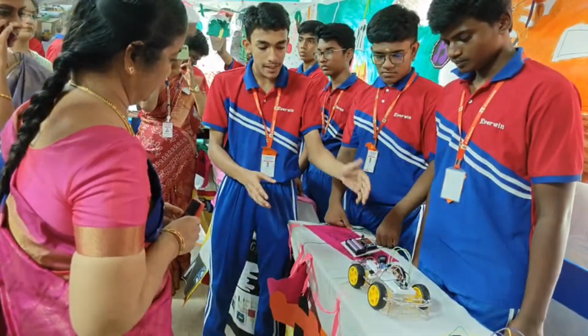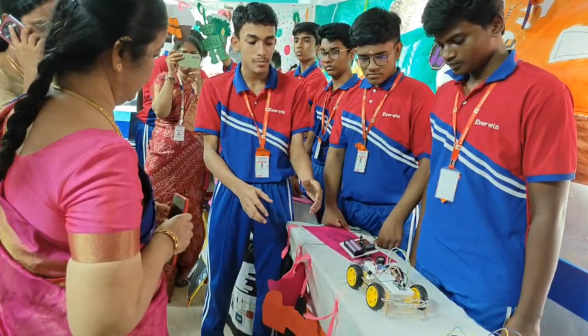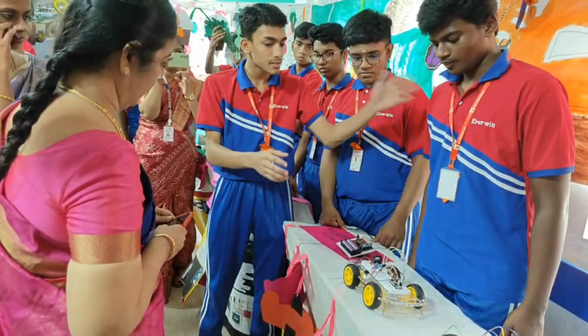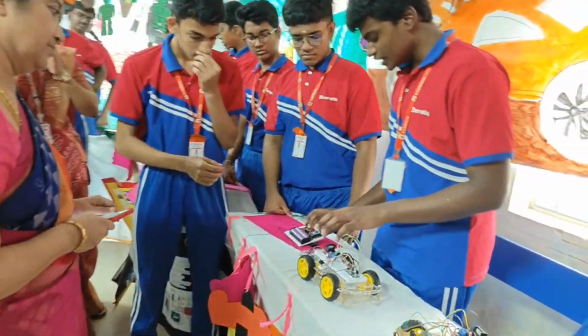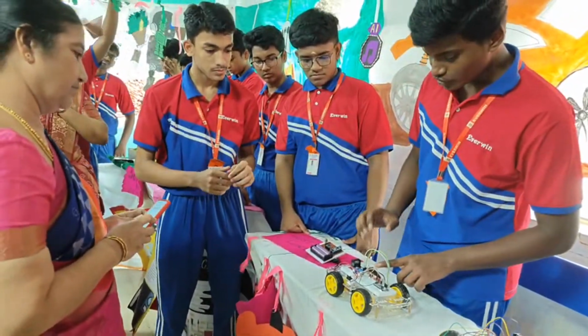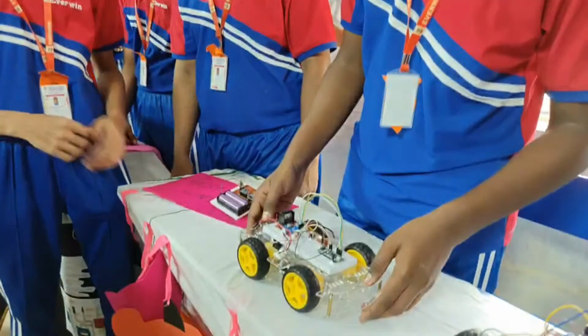So we have developed an LCD type gesture control car which takes readings from an accelerometer. Now let us know about this mechanism. At first, the Arduino, and then the HT12E, which encodes the values and sends them to the RF transmitter. Through RF transfer, it sends them to the L298 motor driver, which instructs the car to move accordingly.